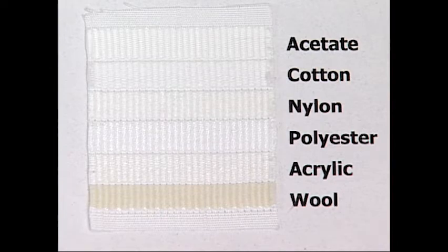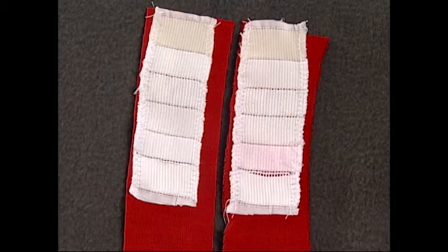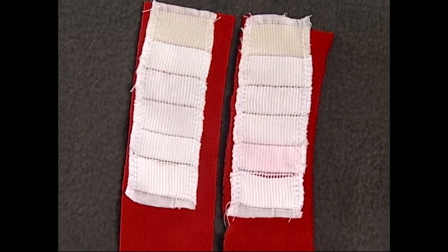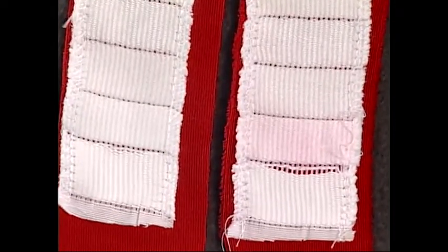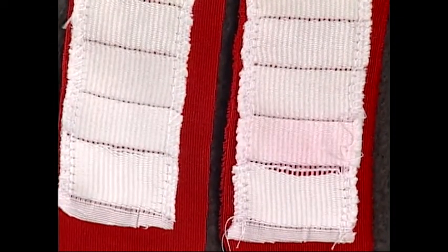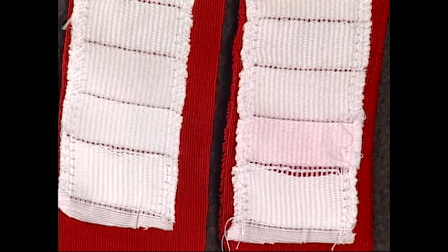Typically, the dye or colorant will not stain all fibers, or those applicable, even at the same depth of shade. Some of the multi-fiber bands will stain, while others may not. Whichever stained band of the test strip shows the most contrast will be the one that is rated and assigned a grade. There are 2 multi-fiber strips commonly used.